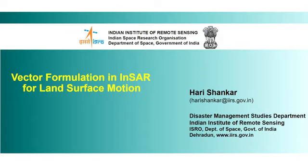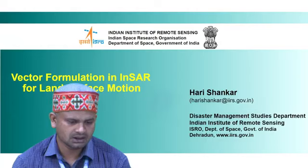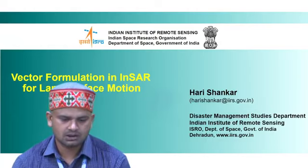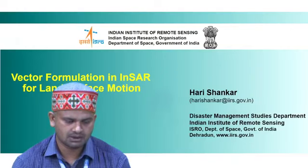So all these three components require some coupling of the InSAR data sets. We have the data sets from the ascending pass as well as the descending pass. If we are able to combine or couple both the outputs of the ascending as well as the descending passes, then by coupling we can calculate the x, y and the z components of the deformation vector. But in fact all three components are not possible from the two passes. So we can calculate only two components because of the practical limitations.